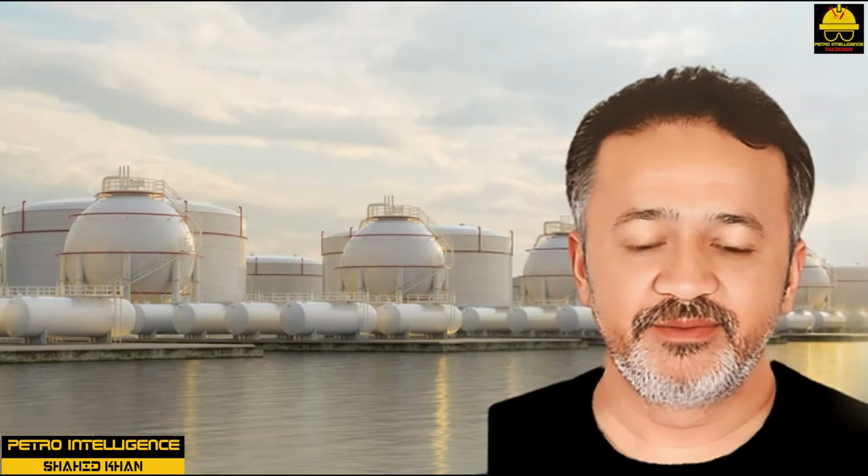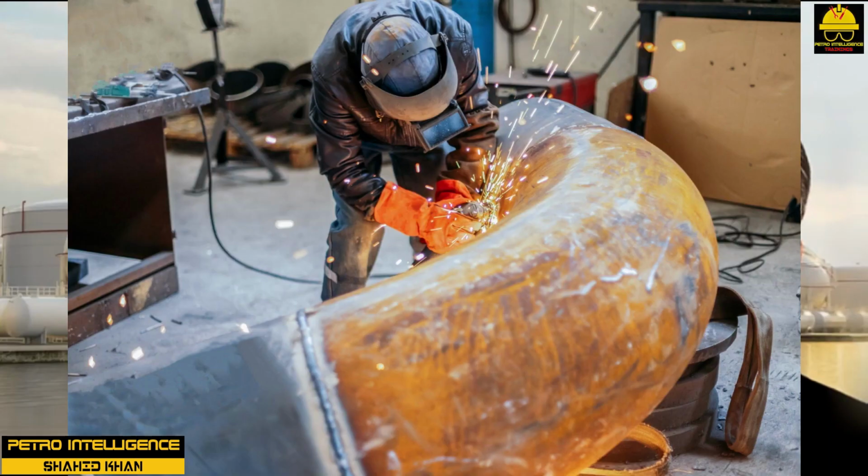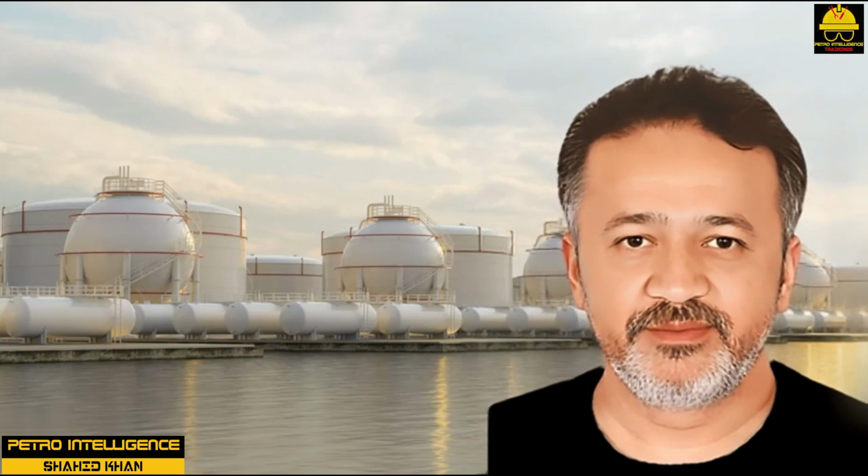Welded piping. Two types of welding may join piping as shown in picture. In butt welded piping, the parts to be joined are the same diameter and are simply welded together. In socket welded piping, the pipe is inserted into a larger fitting before being welded. Socket welded fittings are usually used in 2-inch size and smaller because there is less possibility that stray weld metal will obstruct the flow area. Butt welding is used in all sizes, but particularly in 2-inch size and larger.